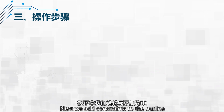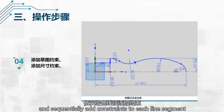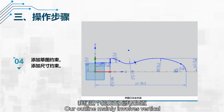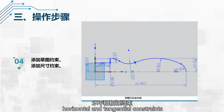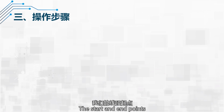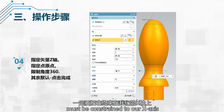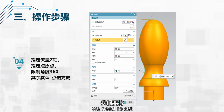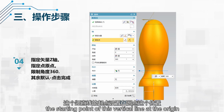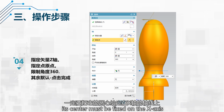Next, we add constraints to the outline. Click the Constraint button and sequentially add constraints to each line segment. Our outline mainly involves vertical, horizontal, and tangential constraints, as well as the point-on-line constraint that we are emphasizing today. The start and end points of our line segments must be constrained to our x-axis. Therefore, we need to set the starting point of this vertical line at the origin, and for the arc with a radius of 10 mm, its center must be fixed on the x-axis.